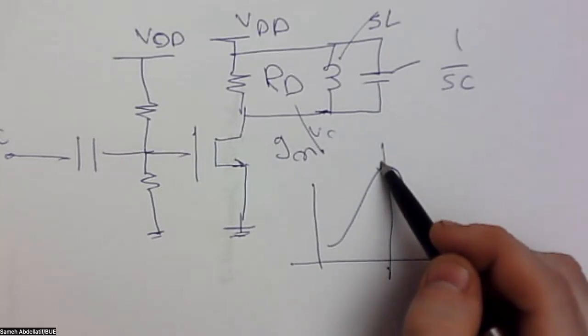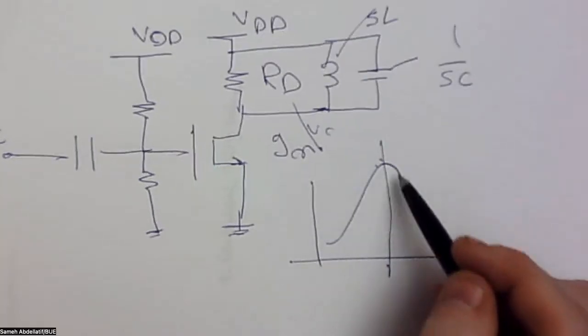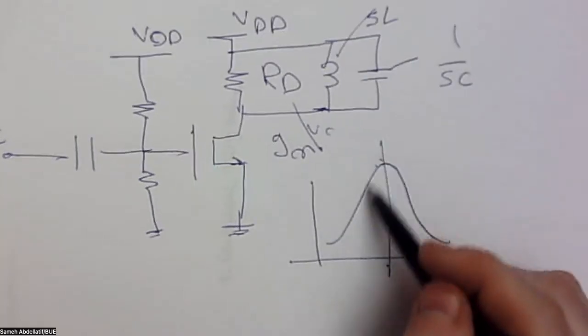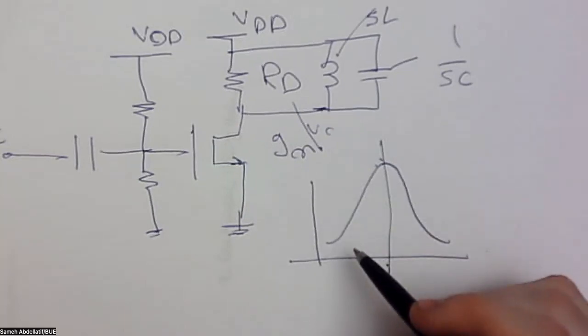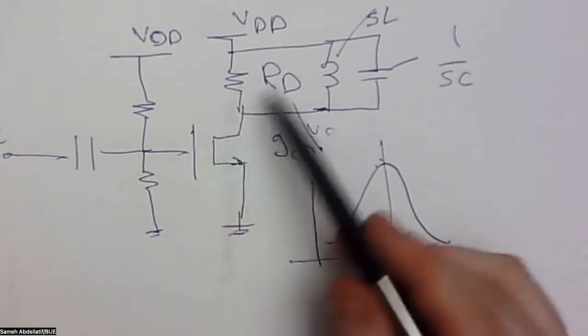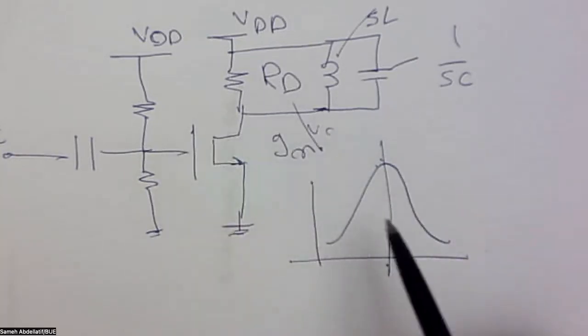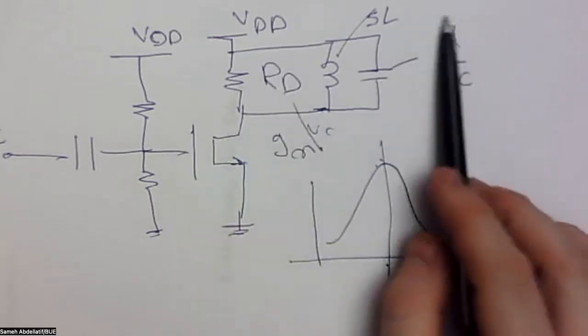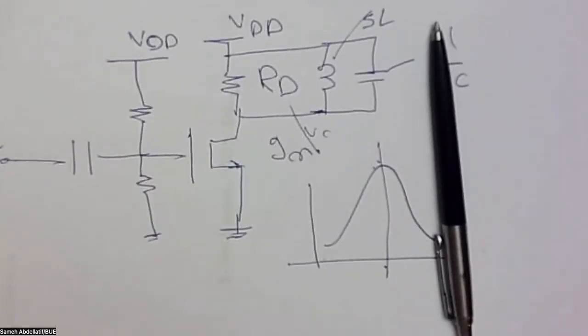This will be your resonance frequency. Otherwise, the response will be a decaying response, making such a resonance bandpass filter. And again, you still have this gain factor due to the MOSFET configuration. And this is one of the typical examples to make a standard tuned amplifier.